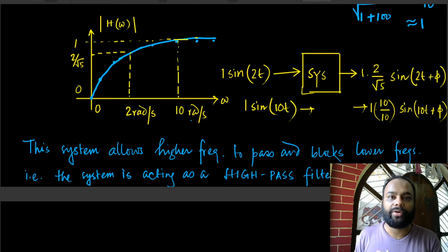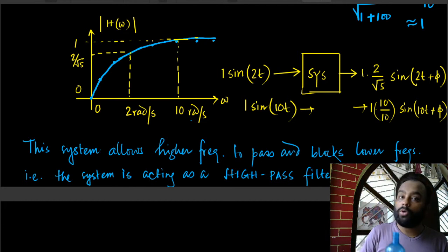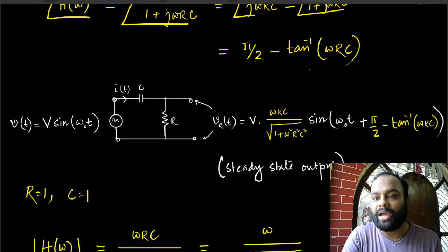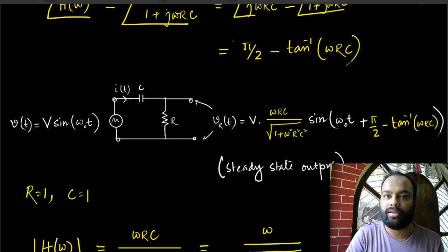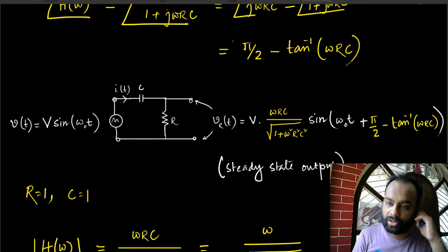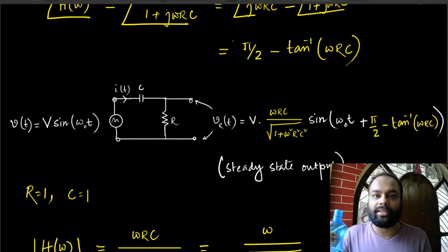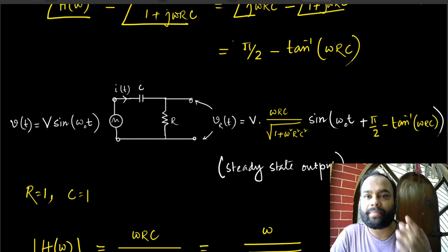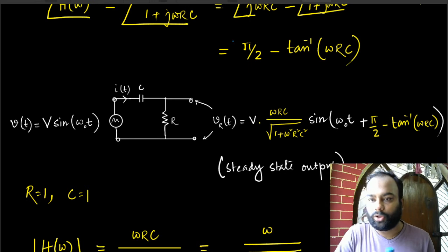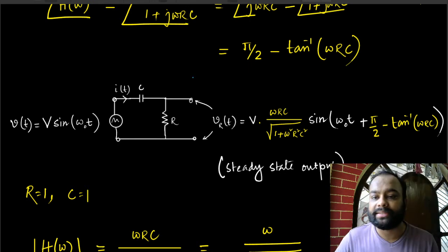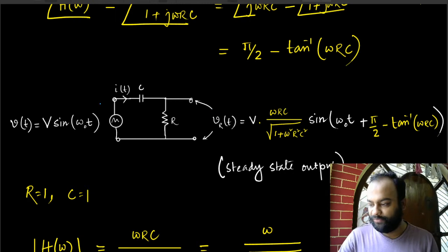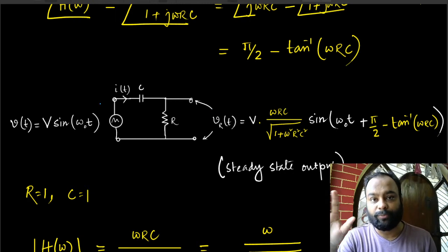Again, feel free to ask any question that you might have up to this point. So we had the same RC series circuit, but the only difference is that we are measuring the voltage across a different element. Previously we were measuring the voltage across the capacitor, and today we are measuring the voltage across the resistor, right? So depending on what we are considering to be the output, the same system can behave as different types of filters. The same system would have different frequency responses.